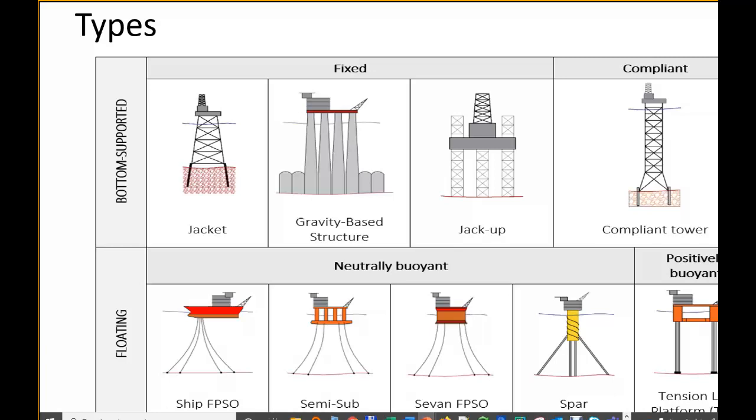They move considerably. They are moored, and they also have to control the ballast, because that gives them the flotation, or how far the topside or the deck is from the mean sea level. If, for example, you're loading too much, in this case the FPSO loads most of the oil production on the ship. If it starts loading too much production, that's going to affect the ballast, the floatability of the vessel. So you always have to be controlling the ballast.